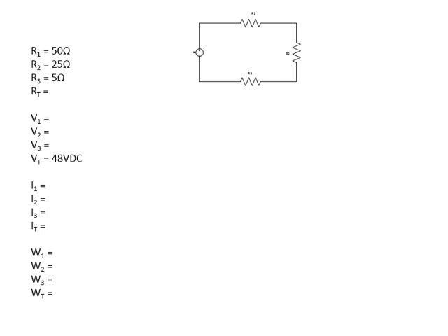First thing that we need to do is find the total circuit resistance, and to do that in a series circuit, the sum of your individual resistances equals the total resistance. So we'll add our 50, our 25, and our 5 ohms, and that's going to give us 80 ohms resistance.